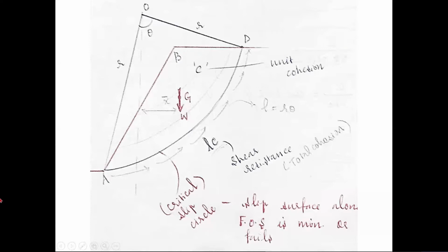So draw the slope. And let us see the condition for purely cohesive soil. So first case, it is C alone. We have only C. There is no phi. Only cohesion. So draw the slope, mark the soil cohesion. Okay, that's it. So this method is called the Swedish circle method. As you can see, we are trying to subtend the arc of a circle here. I don't know where this slope is going to fail. I don't know whether it is going to be a toe failure. I don't know whether it is going to be a face failure. That is why I have these light lines here.